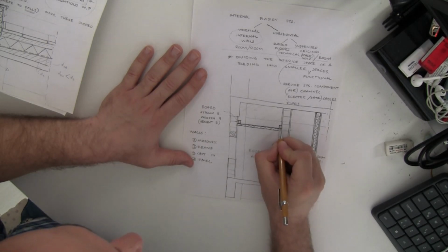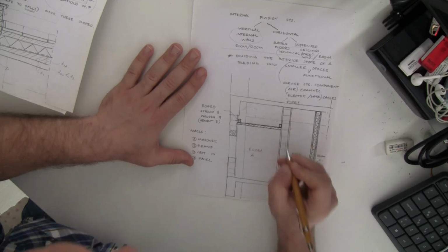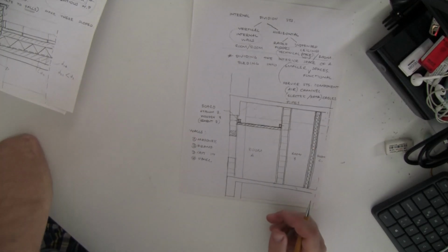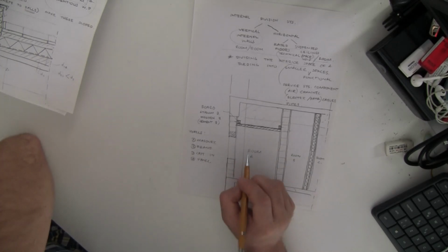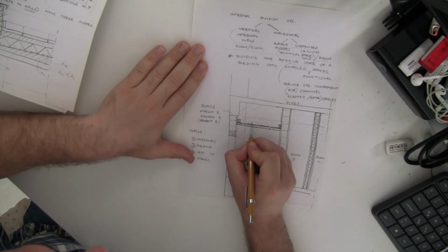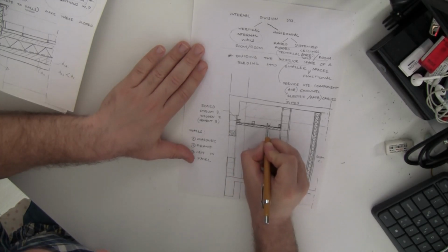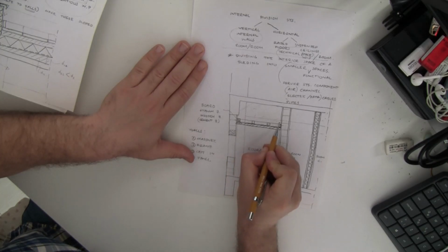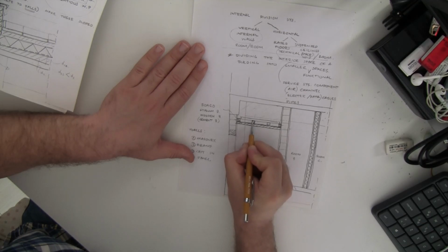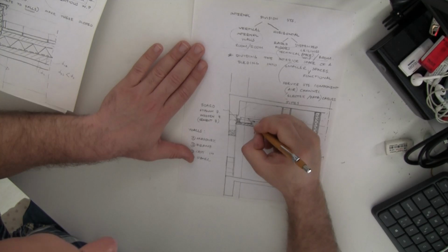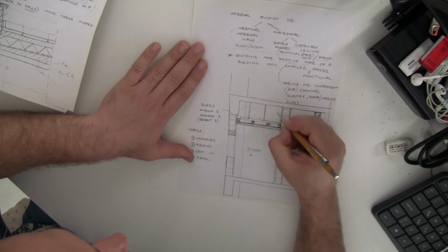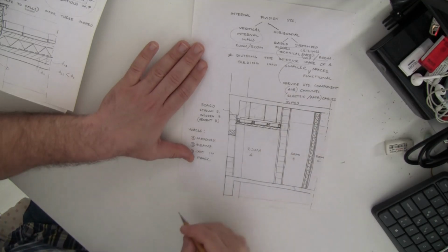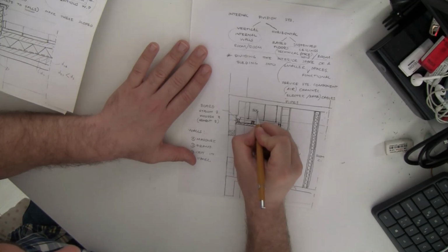Okay, so we are going to get a profile made of wood or made of lightweight steel or made of structural steel. And we are going to tie them to the walls. And then we are going to generate a substructure like this. And we are going to convert it into a grid. Okay, and we are going to hang that thing to the ceiling on top. Okay, so this is suspended ceiling void.